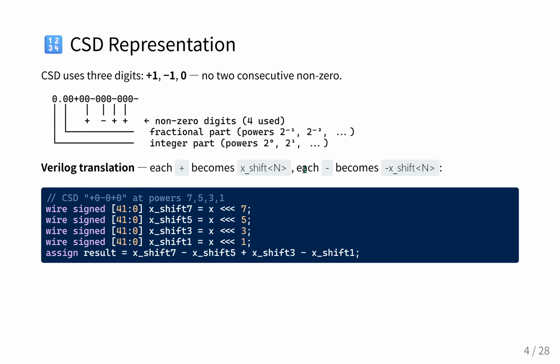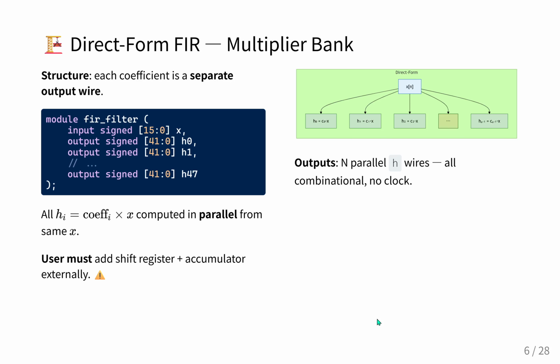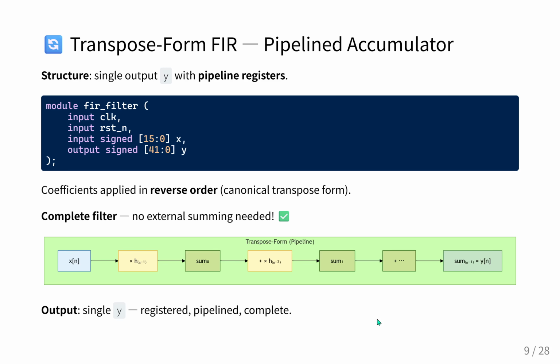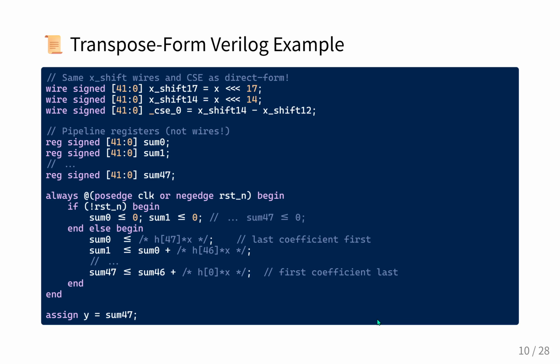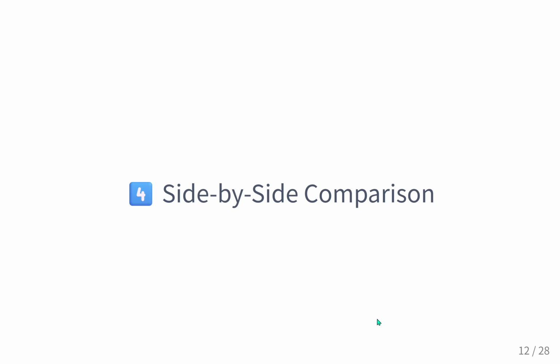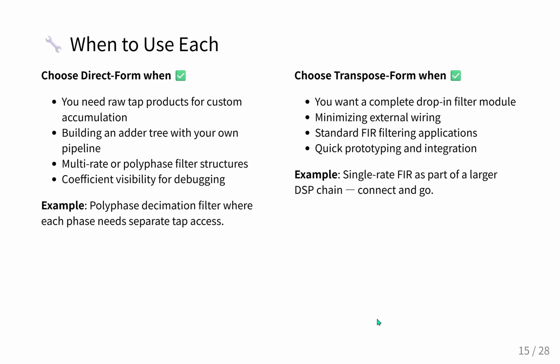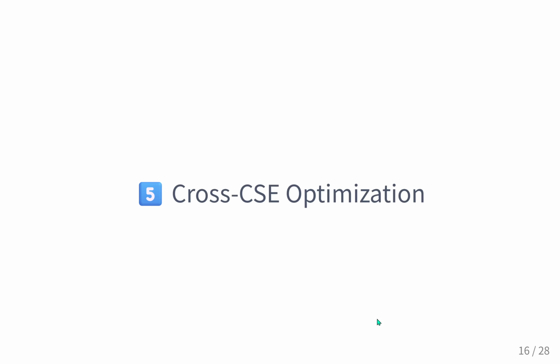You've demolished the factory. But the developer doesn't actually stop there. No, they don't, which is crazy. Right. Once you've broken these 32 multiplications down into a series of shifts and adds, they introduce a second layer of optimization. Oh, the cross CSE. Yes. Cross CSE, which stands for Common Subexpression Elimination. Yeah, and the underlying logic of CSE is just pure pattern recognition.